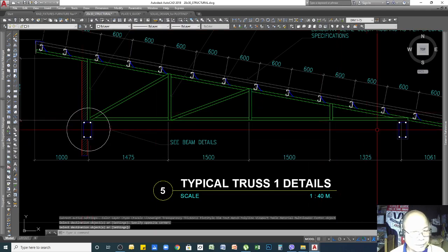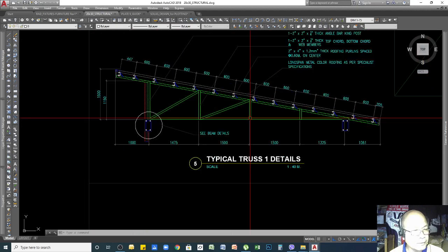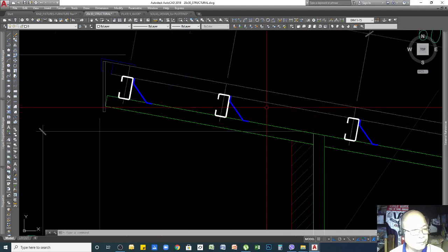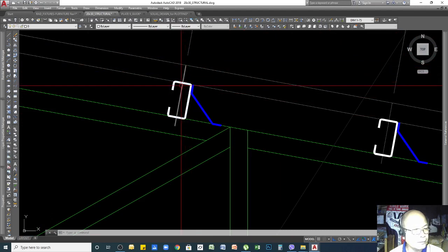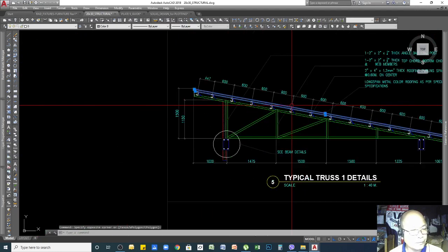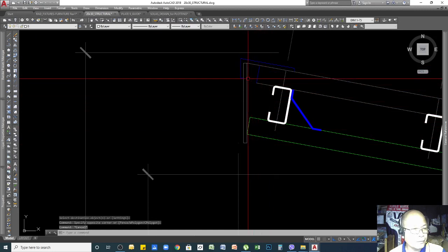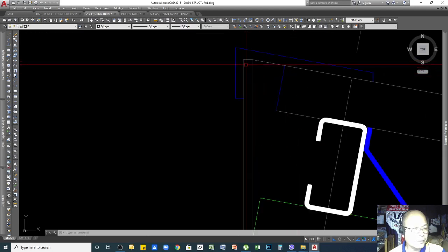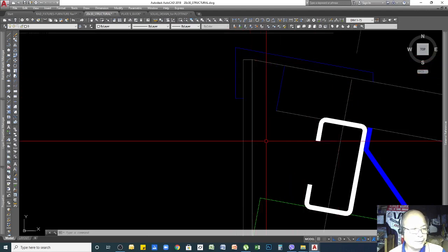So the roof beam is here, and then my trusses are these green color lines, and then I indicated the C purlins. This is the nailer, where the screws for the metal will go, to these C purlins, and this is my roofing material. And then I provided a fascia here to have a better look at the end of my roofing, and this is the flashing to seal the gaps so that it will prevent water from seeping in.